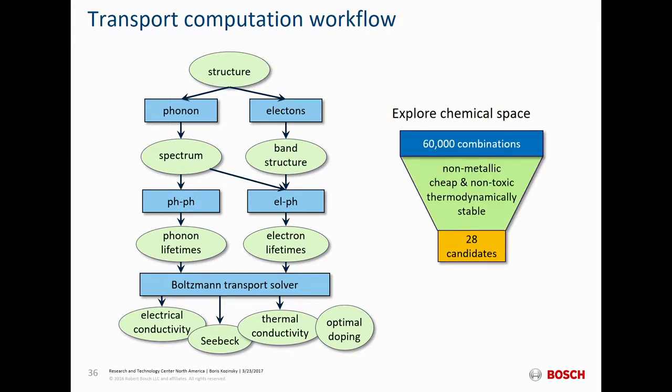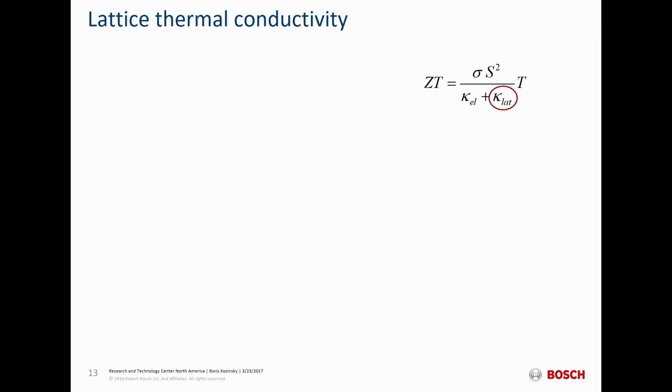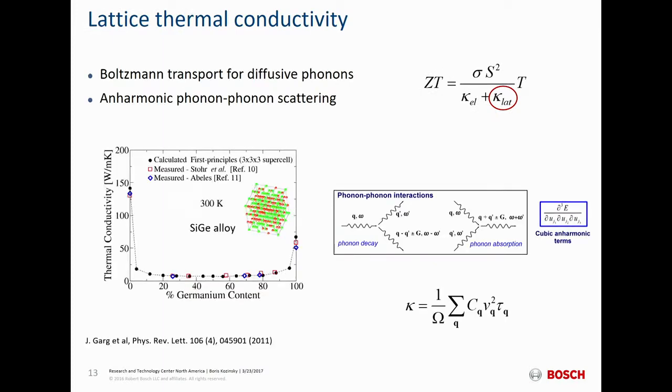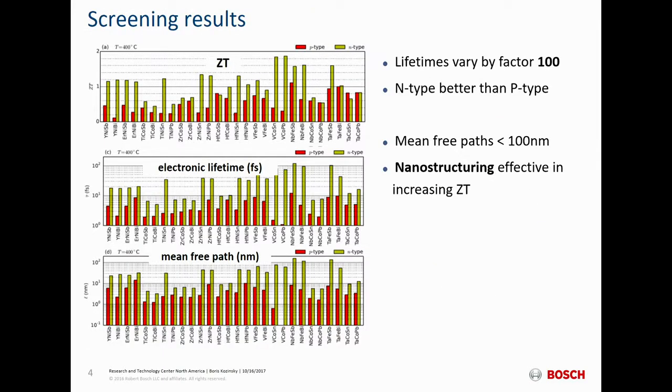And we started doing this for lots and lots of materials, first narrowing down by composition within the half-Heusler family to only select the semiconducting ones and throw out the metallic ones. Then from the pre-screening, we ended up with a set of 28 interesting materials that produced properties like this. So for lots of these different alloys in the half-Heusler family, we have these ab initio predictions of ZT.